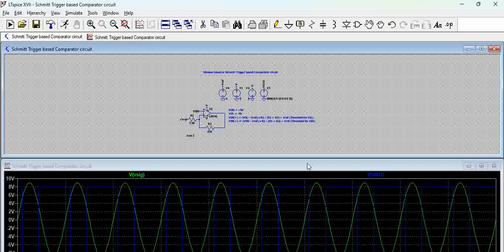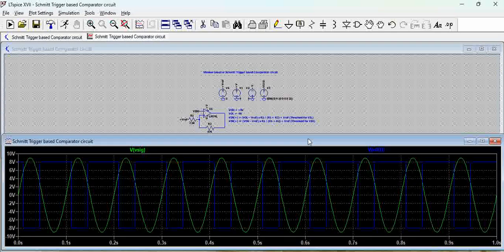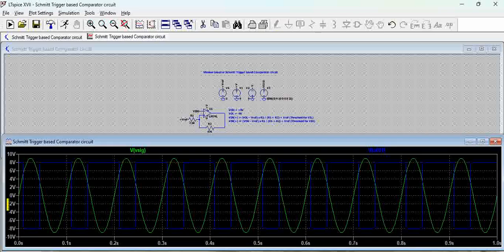Now you can see here, when we simulate this circuit, this is the input, which is minus 9 to plus 9. This is minus 9, this is plus 9. So there is a sinusoidal signal which is expected here. And what is happening here is once the signal goes high, you can see the sinusoidal signal is going high, and when it reaches approximately, let us put the cursor around 5.5 volts, you can see when the signal crosses this, it has gone low.